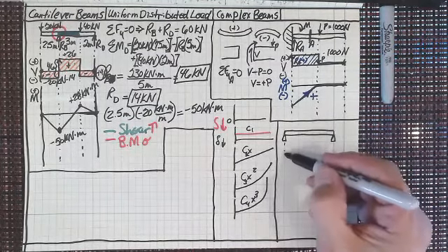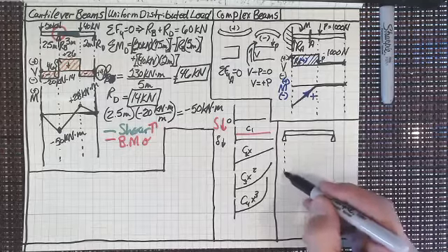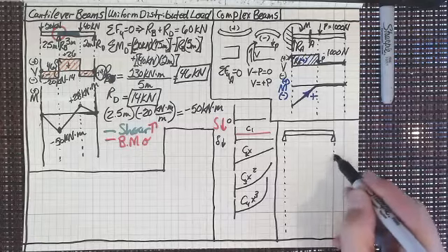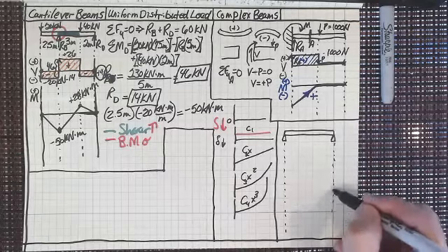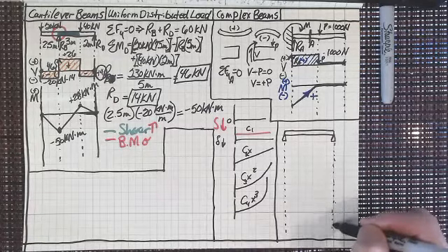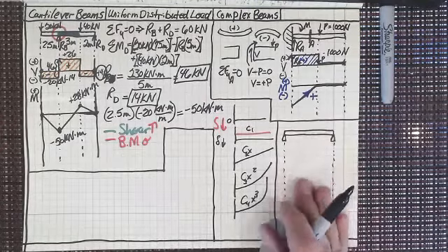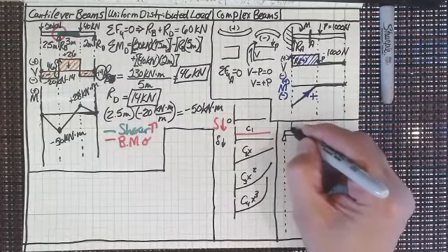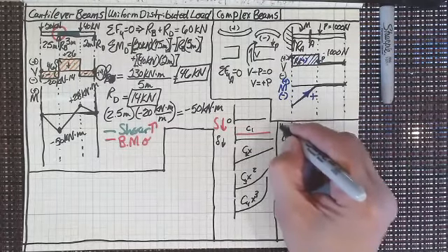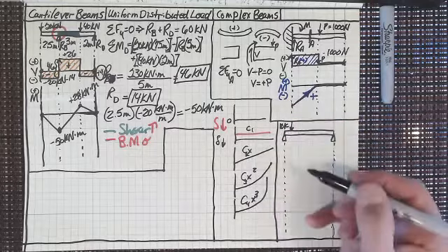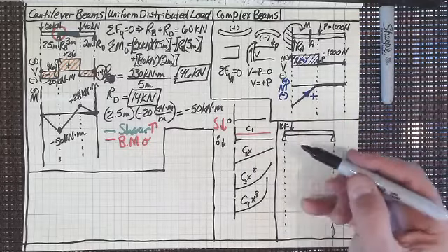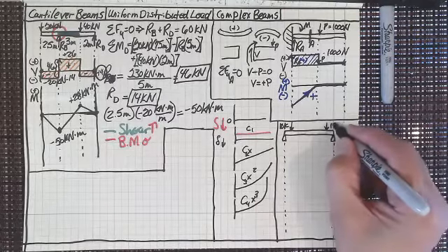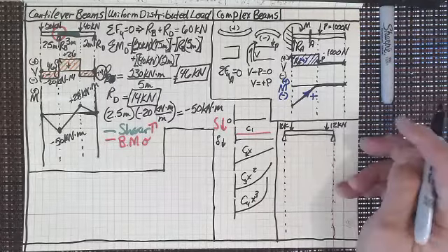So I'm just going to drop my lines down here for my shear force diagram and bending moment diagram. I haven't even shown you what the loading is, and you're already chomping at the bit to solve the problem. Isn't that fantastic? So I've got 1 meter in is going to be 10 kilonewtons. Now I'm just going to put 10K there, but I think everybody knows what that is. And then 1 meter in from this end is going to be 12 kilonewtons, right?